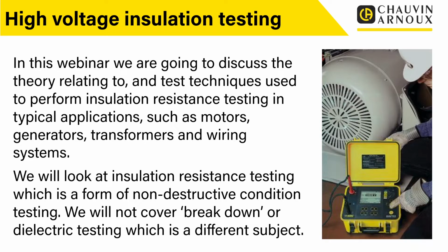We're not trying to prove what voltage we can use to break this equipment, or what voltage we can use to get the insulation to flash over under surge conditions. What we're doing is using these high test voltages, this insulation resistance test, to non-destructively test and monitor the condition of insulation. That's where this differs from something like flash testing or dielectric strength testing. We're not looking to break it down, or to put this insulation under so much stress that it may get damaged. We're looking to do non-destructive testing so that it's repetitive and we can continually monitor and compare the conditions over time.